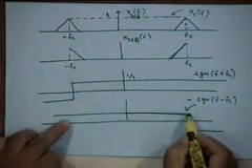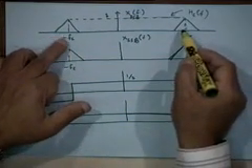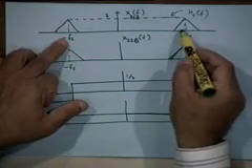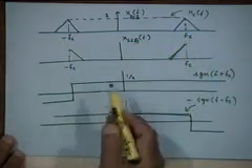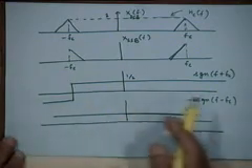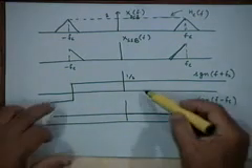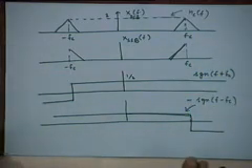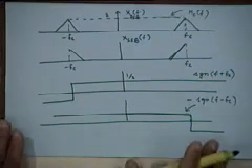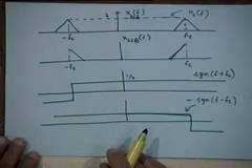So this will give you the ideal low pass filter that you are looking for, with the transfer function value equal to 1 between minus FC and plus FC, and 0 below minus FC and 0 above plus FC. I am doing this just to do some simple manipulations so that I can write down the corresponding expression in the time domain, right.